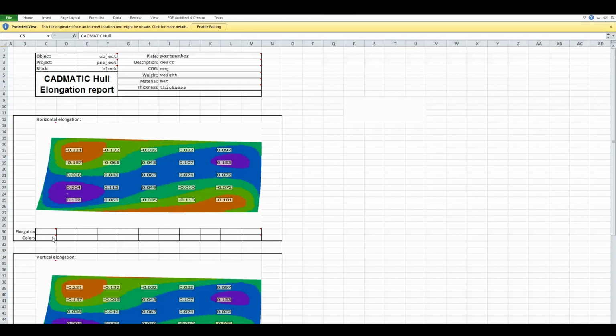The color legends also have keywords here, so they are positioned between the cells with this comment x call or y call. These keywords should either be in the same row or in the same column. The amount of cells between the keywords determines the step size of the legend. So from first to last, we will have so many colors in the legend.